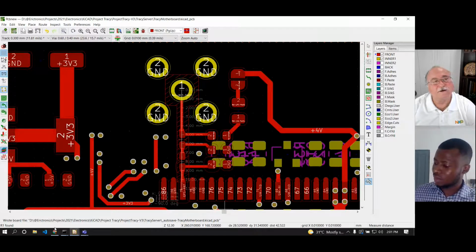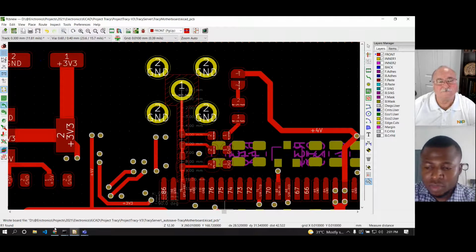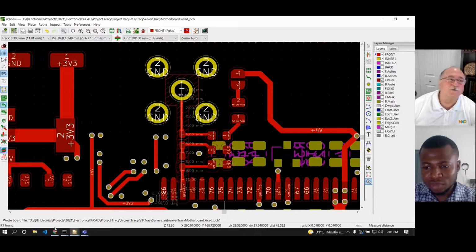And a lot of people get hung up on the frequency, and they think that 1500 megahertz or 1.5 gigahertz is something that's very fast. And in today's world, those are not fast signals. The RF signals are quite often not the fastest signals on the circuit board.